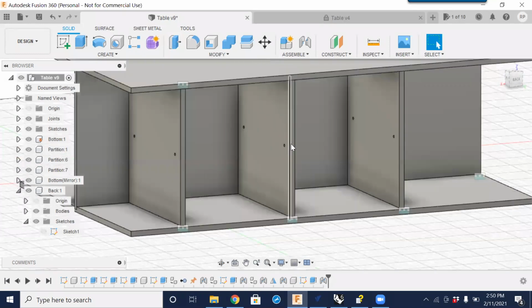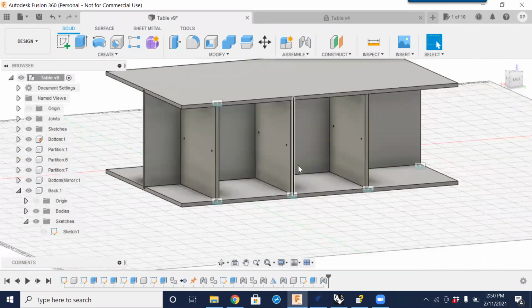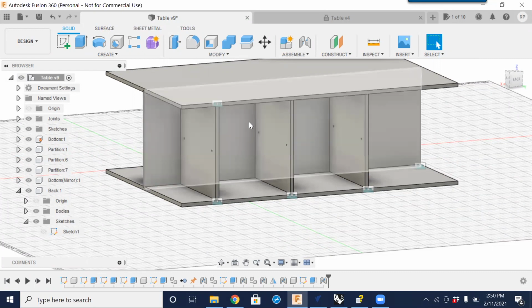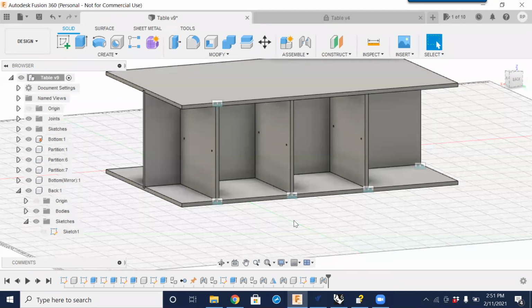So today we have this set to be 3/4 inch material. So we've ordered the material, the lumber company dropped it off, and we found out that they shipped us 5/8 material instead of 3/4. Well, that's probably all right. And they're going to give us a huge discount if we just keep it rather than having them take it back. If we had designed this in just a basic CAD program, AutoCAD or VCarve Pro, I probably wouldn't accept the plywood, I'd send it back, because there's a lot of time in changing everything over to the new material thickness as far as the dados and everything else.